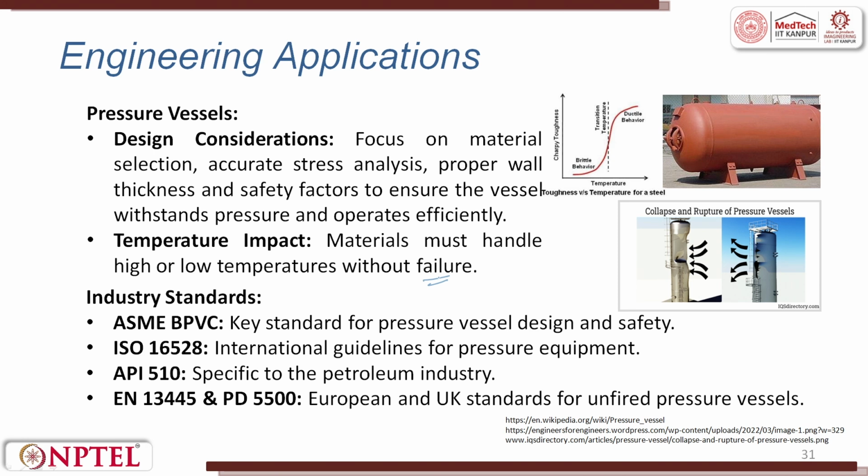There are several industrial standards. ASME BPVC is a standard which is used for pressure vessel design. ISO has pressure vessel design requirements, which are separate. Then API is specific for the petroleum industry. EN 13445 and PD 5500 are the European and UK standards for unfired pressure vessels.